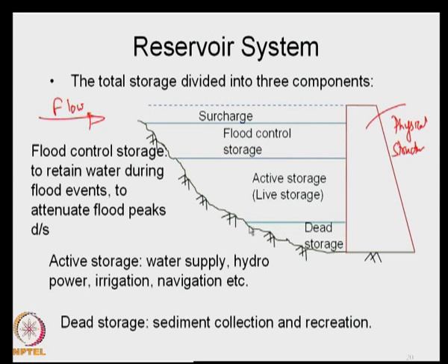We provide what is called a dead storage, which means the water in this storage we do not use. We do not extract the water. Now, this dead storage is essentially provided to accommodate the silt or the sediment that comes in.